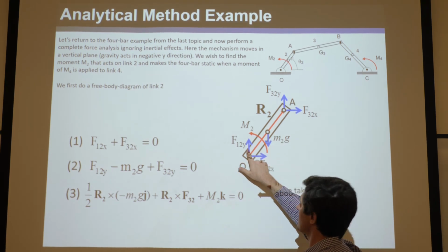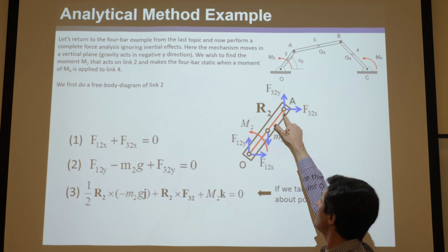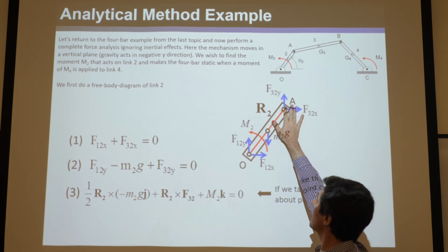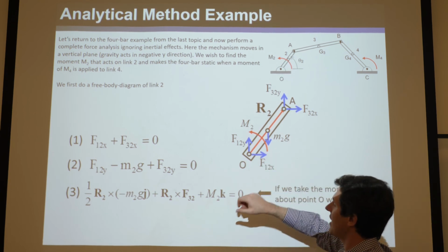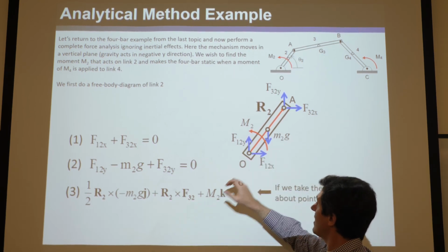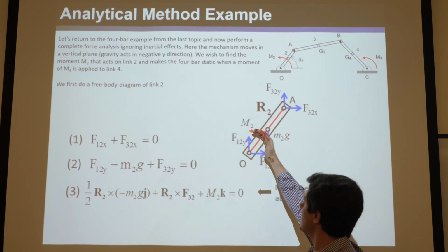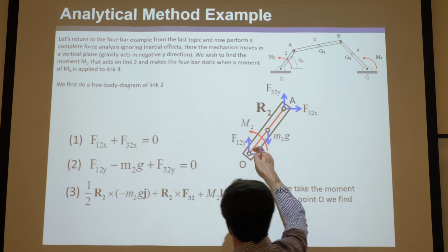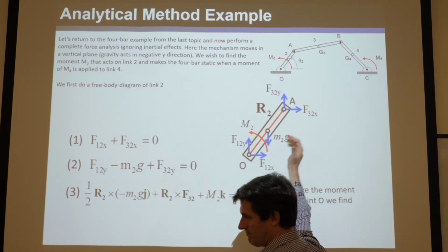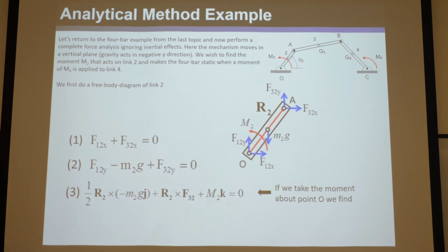And of course, these forces don't exert a moment about O. And then you'd add it to R2 cross the force up here, which in this case we're just combining into solid F32. Okay, and that's that. And then we have to add it to this just moment, this pure couple M2, which we could have drawn anywhere because it doesn't have a location. This is not saying it's about this point. You could do it anywhere. Add it all together, and it equals 0.